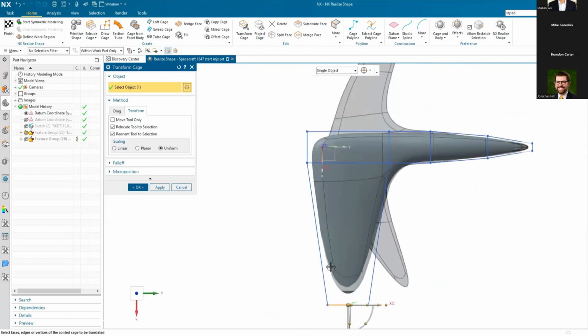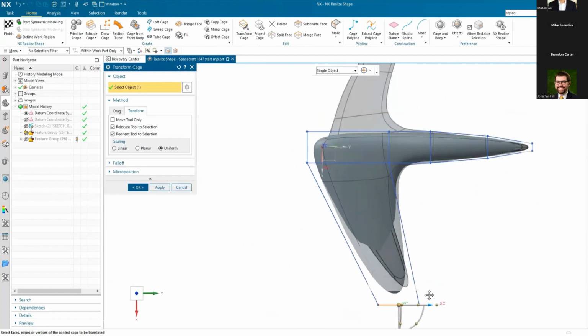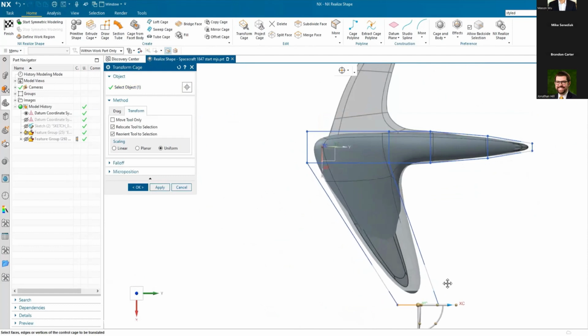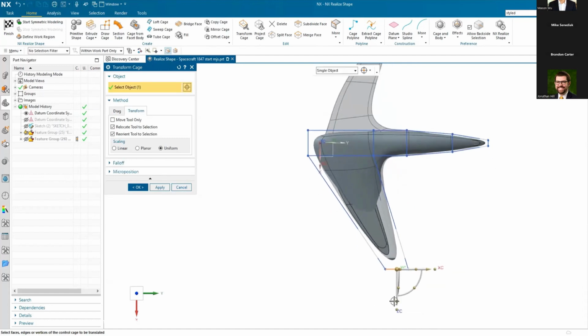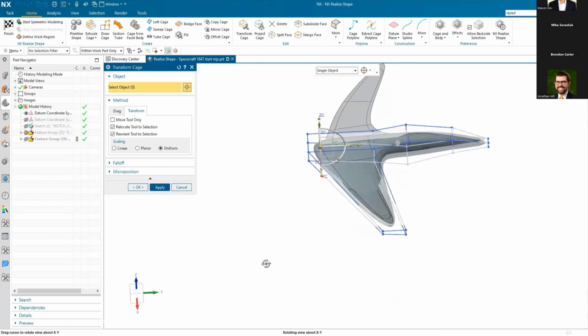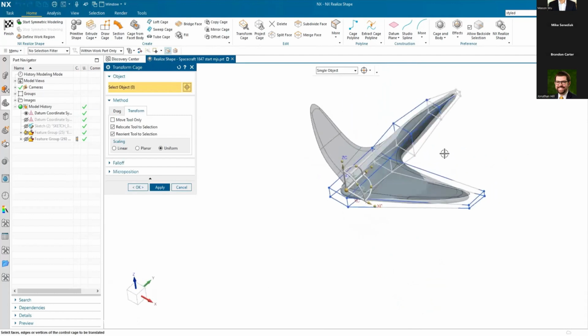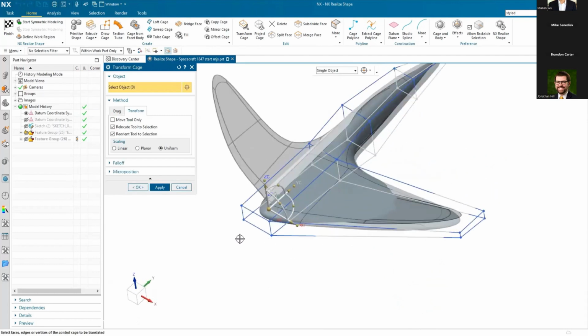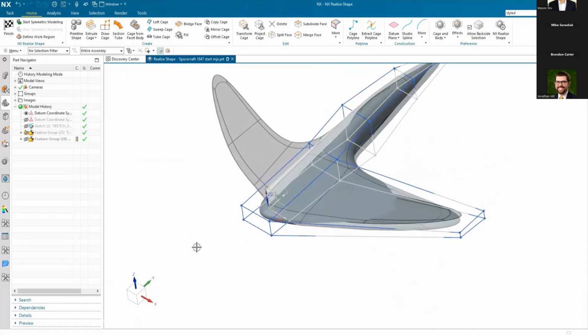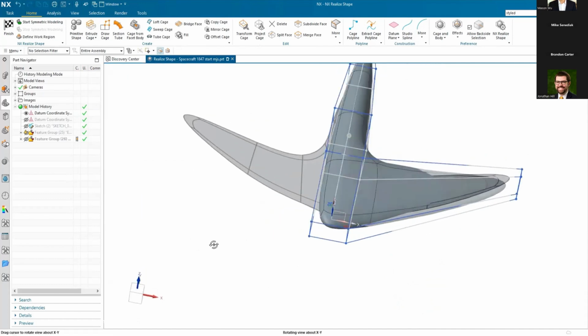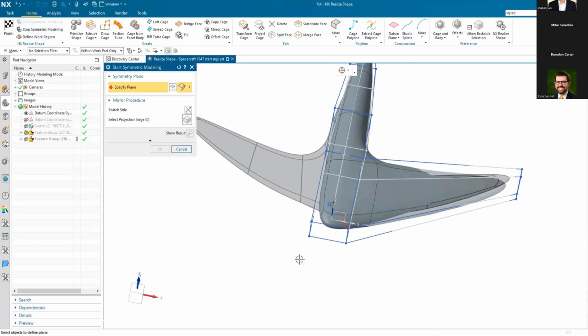So this, as you can see, is why it's called subdivision modeling. You can see by dividing up the cage, putting more definition into it, hence the name, subdivision modeling. And so not only can you work with specific areas of this, but you can also take advantage, as we will here in a moment, of symmetric modeling, right? So if I don't want to have to repeat those same steps on the other side to create the other wing, I'd like to just use the symmetry and drive that to the other side of this particular craft that we're laying out.